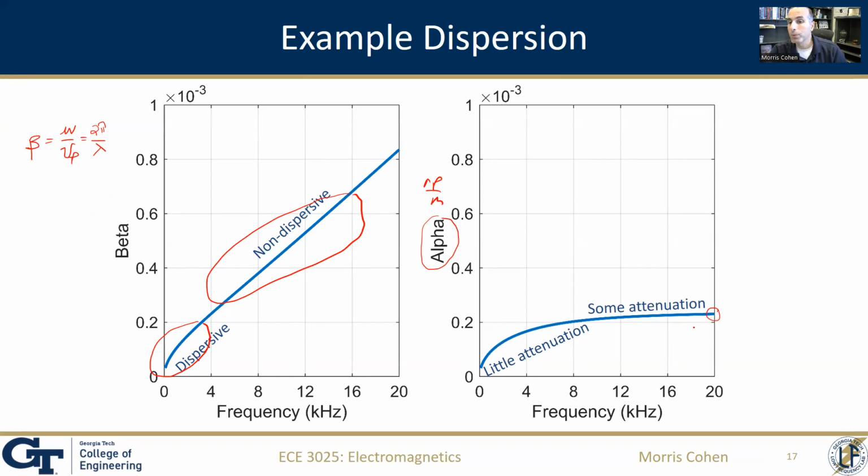So at a certain point, this attenuation would get too high if you increase your frequency. So this cable is optimized for the audio, but I would not advise ever using this for, let's say, a gigahertz signal. Clearly, this cable would not work. By the time this attenuation gets out to 1 gigahertz, it would be way too high for this cable to be useful. But it clearly works pretty well in this scenario.